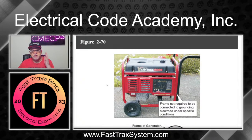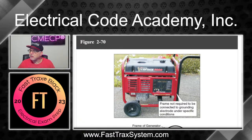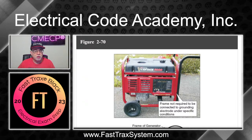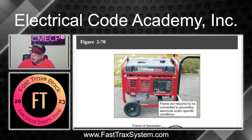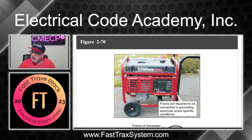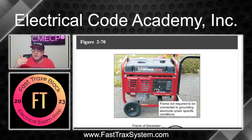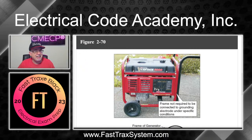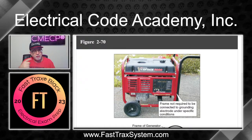All right, so let's look at this real quick. Here's a very standard generator. This is a 5,000 watt generator. You notice here's the metal frame. It's on non-metallic, plastic wheels, so it is not in contact with the earth. Now, this frame is not required to be connected to an electrode under the specific conditions that we just read. Obviously, here are the receptacles built into the generator. That meets one of the components. The other aspect of not having to have the electrodes is that it has to have the connection from the neutral point and from the equipment grounding terminal connections on these receptacles over to the frame. All of that has to take place.